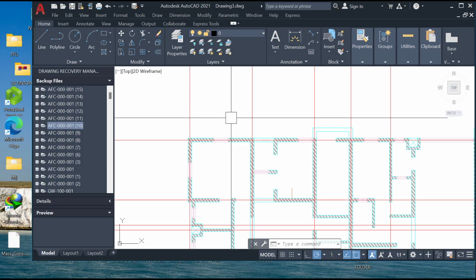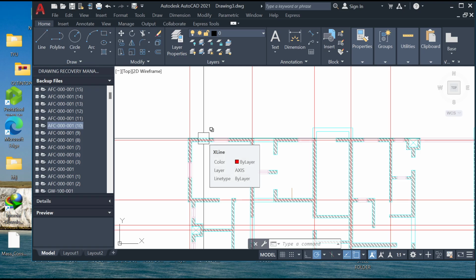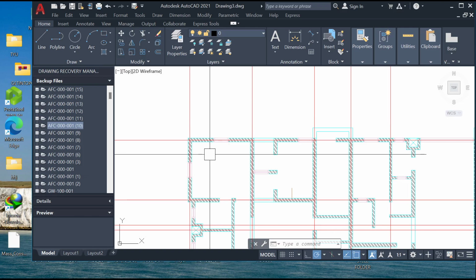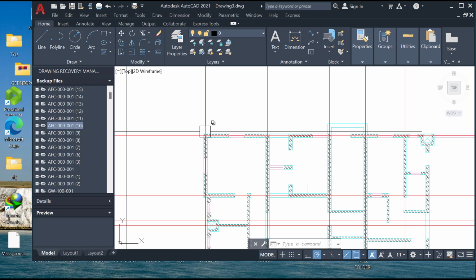But as time goes on, I'm going to be teaching you the principles in the design of columns that are spanning 10, 15, 20 meters. But for now, because this is a beginner class, let's stick to just the principles. Like I said, your column to column span should not exceed 5 meters.